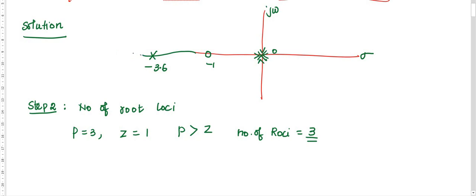You have to consider one point here. The point is P. Take this point. Towards the right, how many poles are there? There are 4 poles and zeros. If there is an odd number of poles and zeros towards the right, then a root locus exists. If there is an even number, there is no root locus at this point. Okay, I am going to erase this.